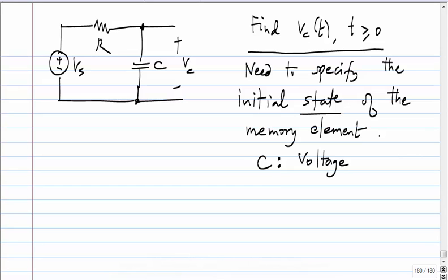You know that its net effect has been to put let us say 1 volt across the capacitor. Similarly, the same for an inductor. You do not need to know the voltage from t equals minus infinity to now, right. All you need is the current at t equal to 0, or whenever you want to start solving the problem. Okay. So, these two also have to be specified. Okay.